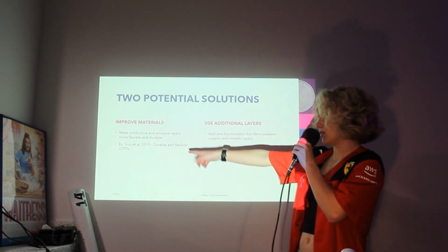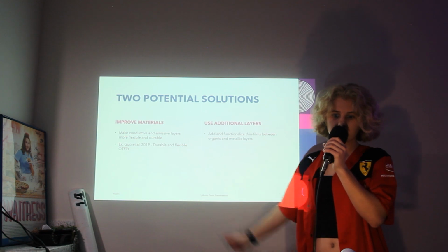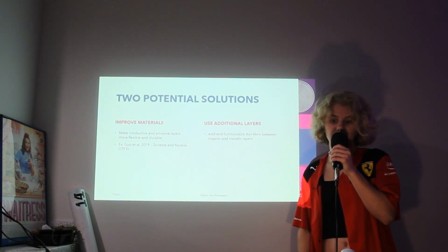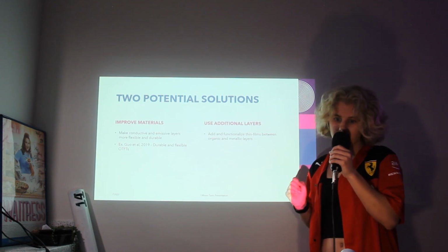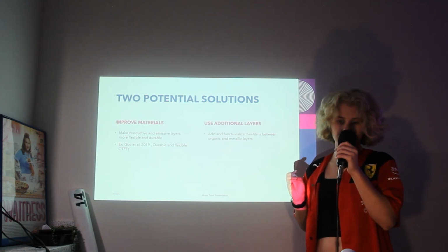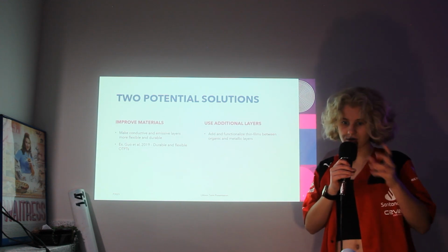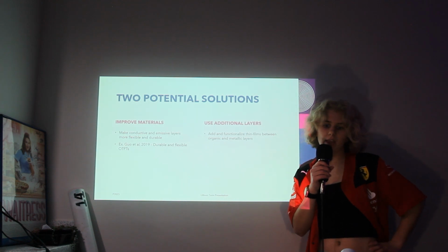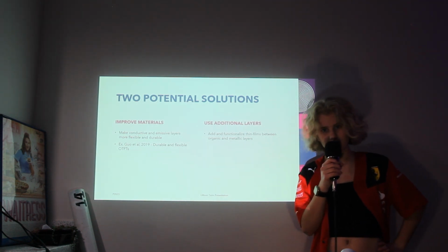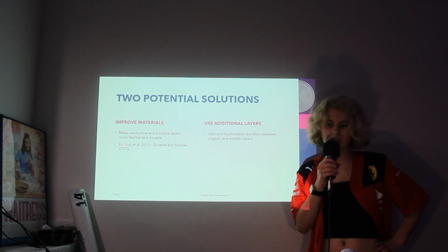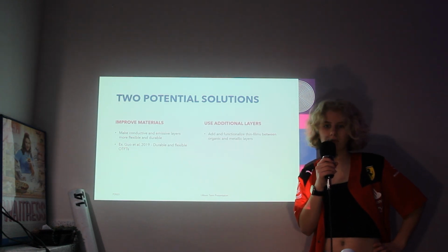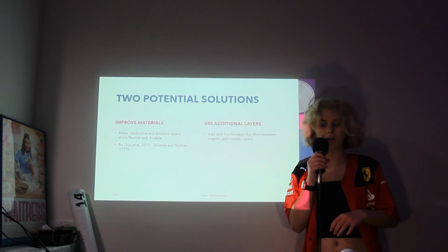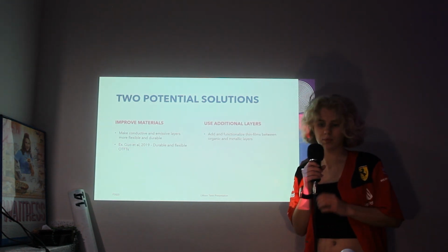So in the 2019 GWO study, researchers developed a flexible and semi-transparent organic transistor and circuit by using a polyphenylene oxide dielectric. The organic thin film transistor exhibited high mobility and mechanical bending stability, maintaining its electrical performance even after 5,000 times of bending. This development brings us closer to achieving high-performance flexible electronics. The rest of this presentation will cover recent studies on thin films in semiconductors for this purpose.